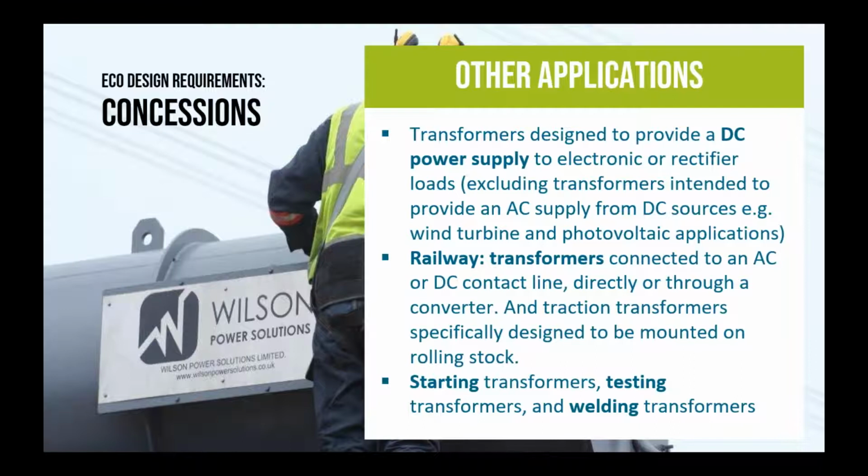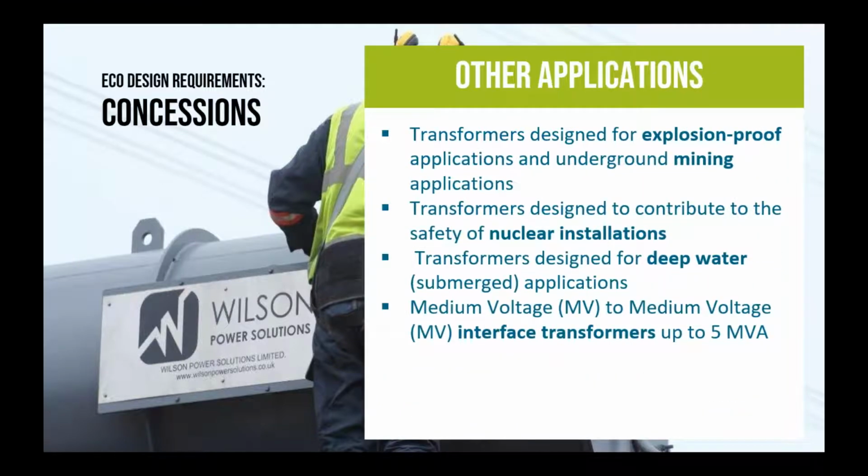So these transformers are manufactured for a very, very specific use. These will be given a concession or an exemption from the regulation. They can be Tier 1 after that date. Continuing, we have transformers designed for explosion-proof applications and underground mining. We have medium or power transformers designed to contribute to the safety of nuclear installations, and then transformers specifically designed for deep water submerged applications, and then some of what they call